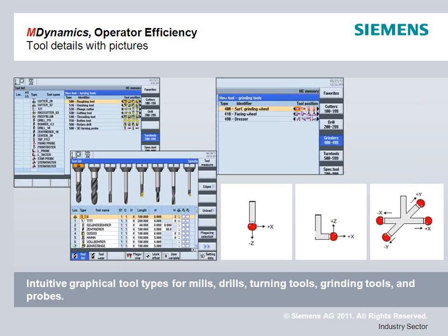Now, while for a lot of places it's not entirely critical to identify the tool types well, there are certain features that can really take advantage of you having defined your tool types correctly. For example, if you're dealing with a part that has a countersink, and you need to say that the diameter of my countersink needs to be 249 thousandths, you say that I'm going to use a drill bit with a 118-degree angle on the tip, and it's this diameter.